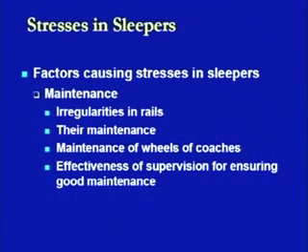Then further, the factors which are inducing the stresses in sleepers relate to maintenance. The maintenance can be of any of the things, maybe the components which have been provided in the track or the track overall. Like there can be an irregularity in the rails, as we have discussed previously during this lecture, taking the example of a joint where two rails are being jointed, but the level of the top surface of the rail head is not the same, it is at a different level. So, if that type of irregularity is there, then it is going to create some effect.